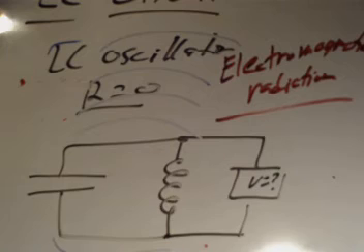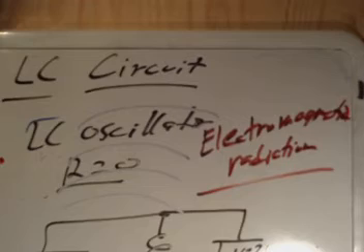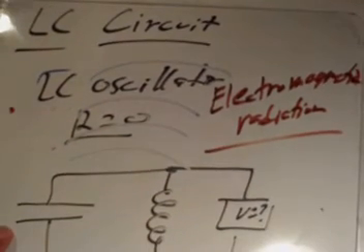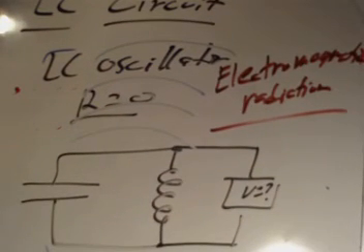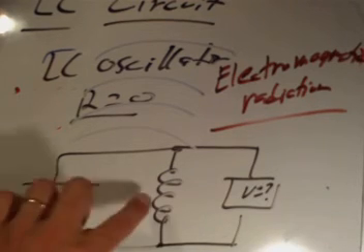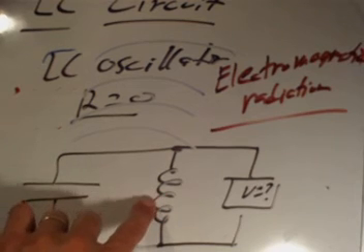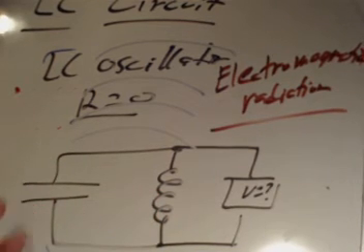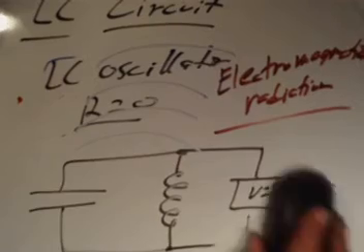So if you tune this oscillation to overlap with the FM band of the radio, you'll hear this oscillation going. Maybe it's a series of clicks or some other background noise. But that's the nature of the game here. That's what happens when you dump a fully charged capacitor into an inductor. If the system is perfect, you will get this LC oscillation happening because of the charge sloshing out of the capacitor into the inductor, and then out of the inductor back into the capacitor, but with the opposite polarity. The system in a perfect world would go on forever.